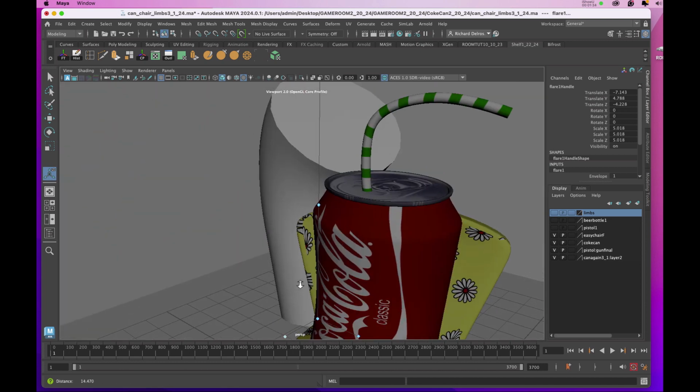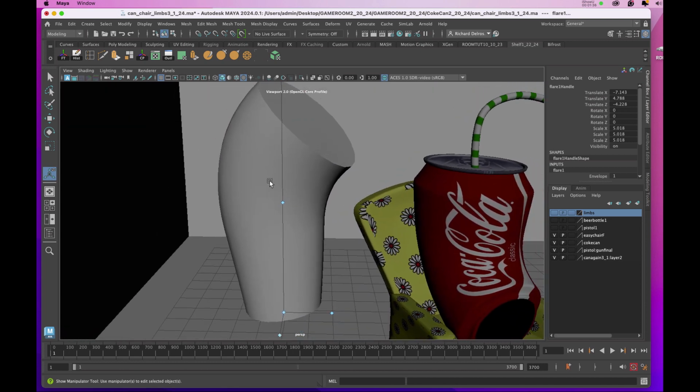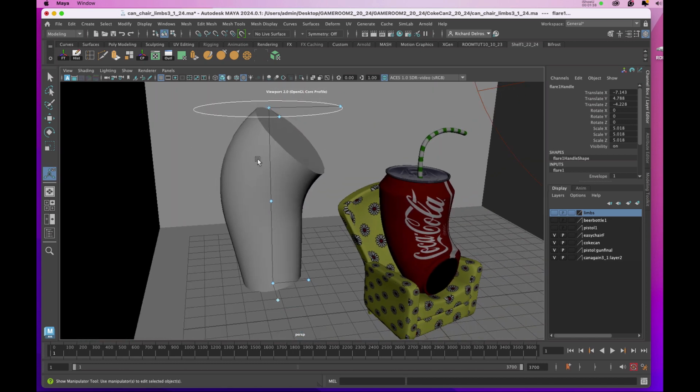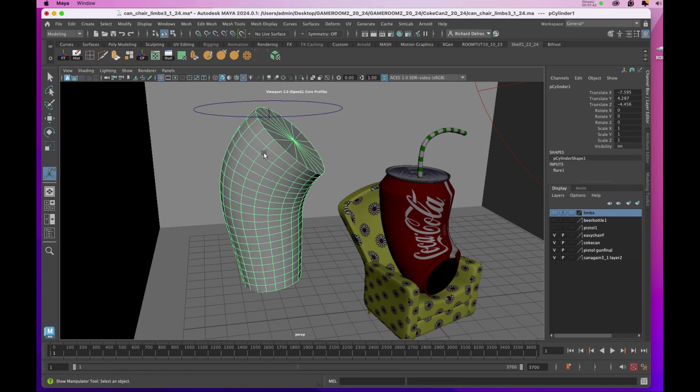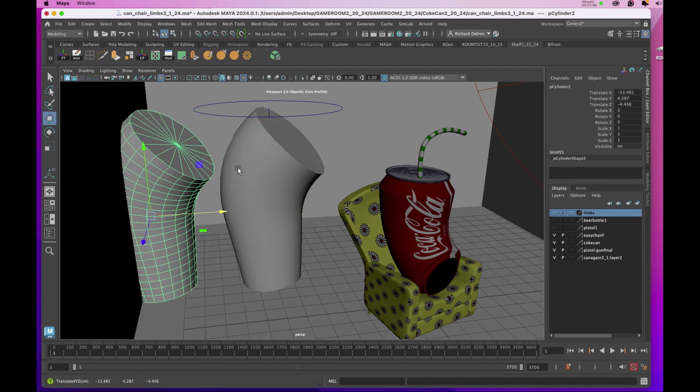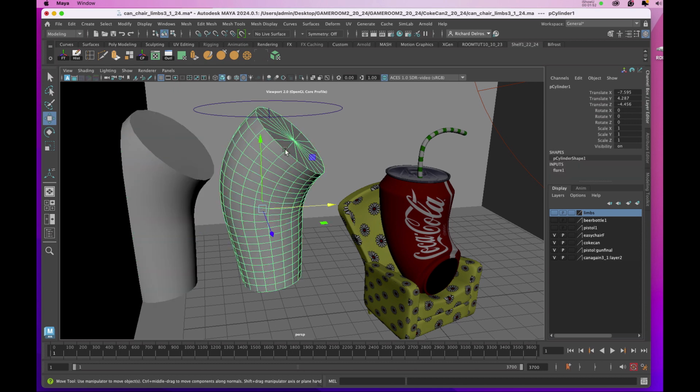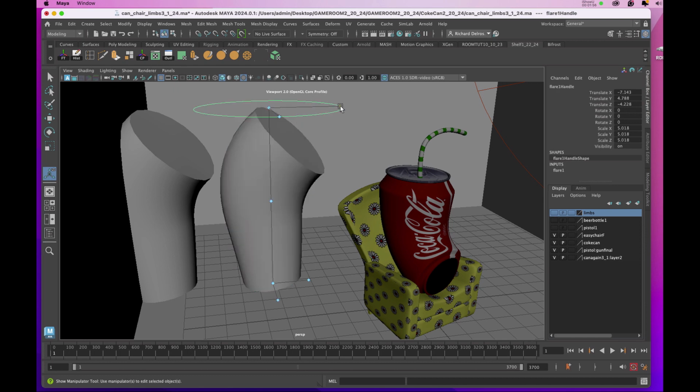So each time you introduce one of these nonlinear deformers, you have to delete the history. It's always a good idea to duplicate this. So if I hit Command D during the process and move it, that's a permanent effect that was left by this one as well as the one previous. So I could go back in here now, and if I wanted to, I could select that tool and re-edit it, and you can see now this one is independent.